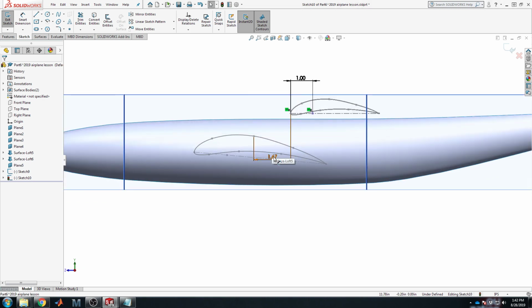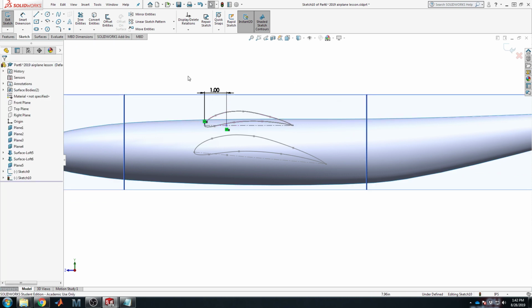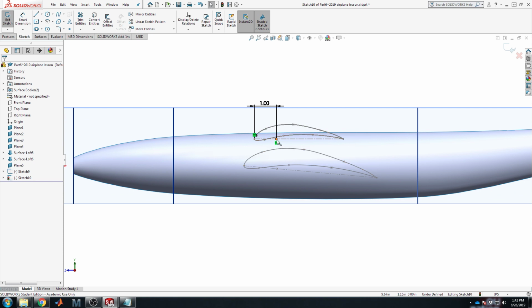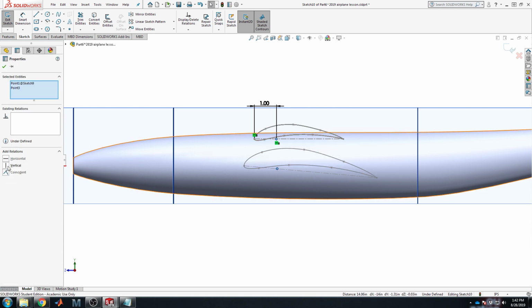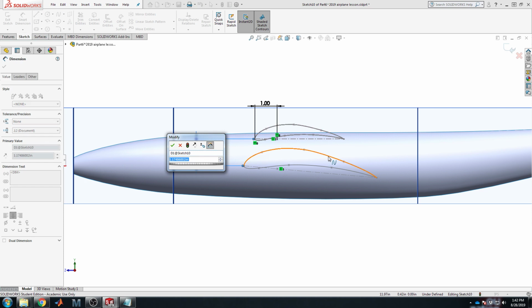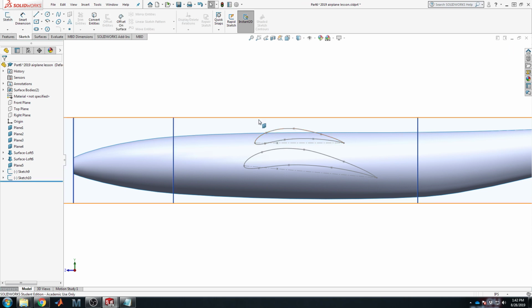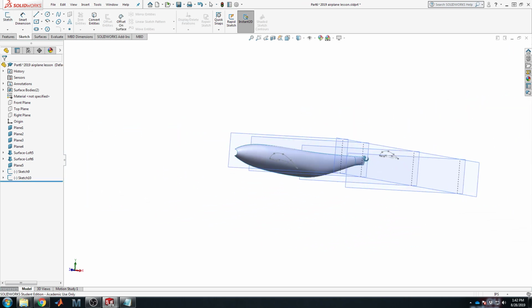Okay, that's why sometimes your relationships break. SolidWorks grabs a different point that you didn't actually want it to be referenced to. But that's all right, because all I'm going to do now is take this point, put it straight over the other point, make them vertical to one another. So that means in the right-handed plane projection, you will have 0 quarter chord sweep, which makes your aerodynamics team very happy. 1 inch leading edge of the tip higher than the root leading edge should be good to go. And this will give us a nice little bit of dihedral to go across the airplane.